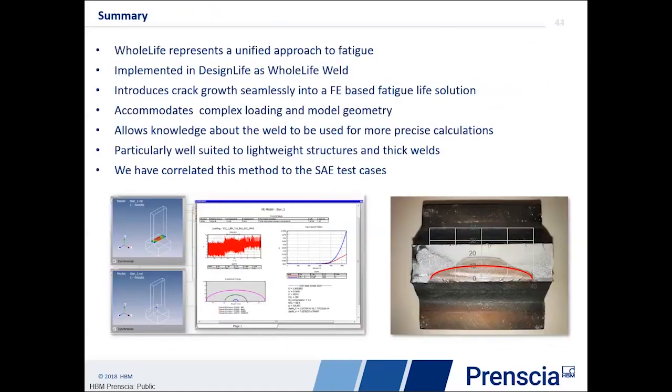So, ending this, WholeLife is actually a unified approach to fatigue. It incorporates both initiation and propagation due to the fact that it's using this blunt notch at the tip of the crack. We've implemented that approach as a weld fatigue calculation inside of DesignLife.